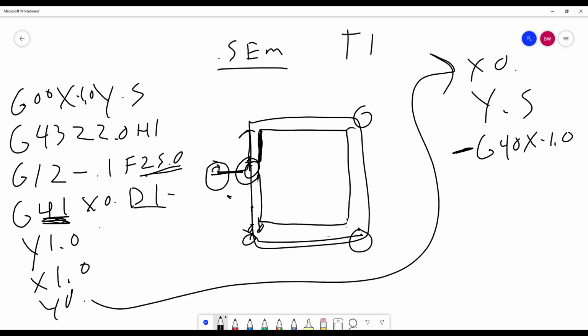You could change the feed rate here to, let's say, F10, 10 inches per minute, whatever. We'll talk about that when we get into the actual example. Okay, so that is a basic linear example of not only using G1 to cut around something, but also using cutter compensation. Okay, so I'm going to take a break here, and then we'll come back. We'll talk about circular interpolation with cutter comp, and then we'll get into programming our example.